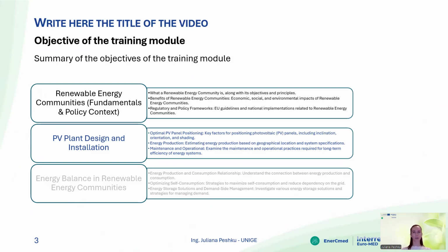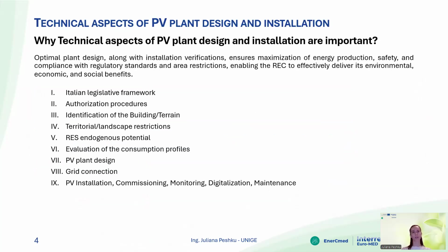As already mentioned, in this training section, we will deal with the PV plant design and installation, defining the optimal PV panel positioning, including inclination, orientation, and shading, energy production based on the geographical location, maintenance and operation conditions for long-term efficiency of energy systems.